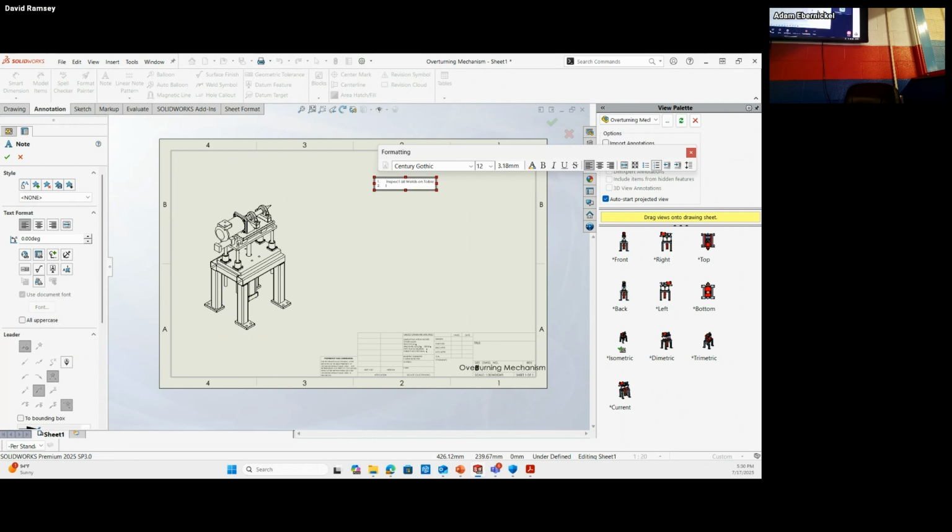I'll come down with a note number 2, and I'll say add washer, split washer, and nut. And then I'll say, let's see, add Loctite for metal to metal, right? So those are my 3 notes.